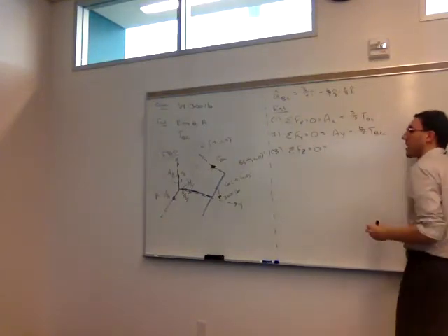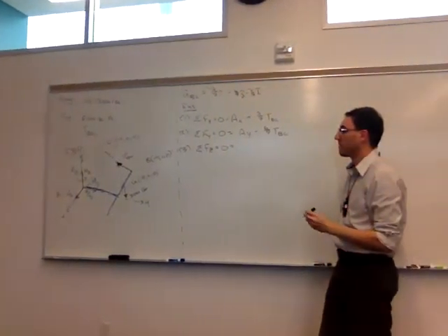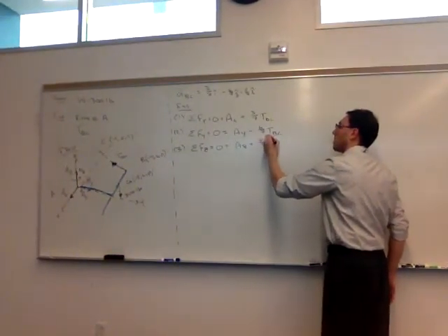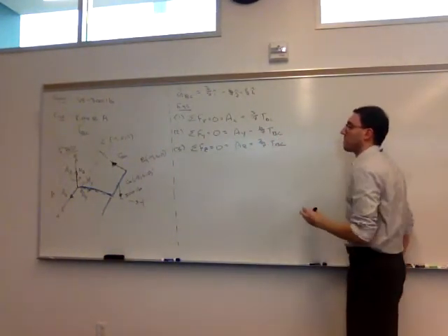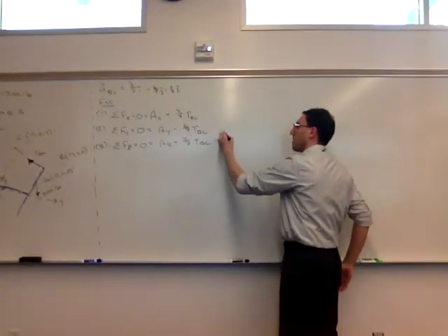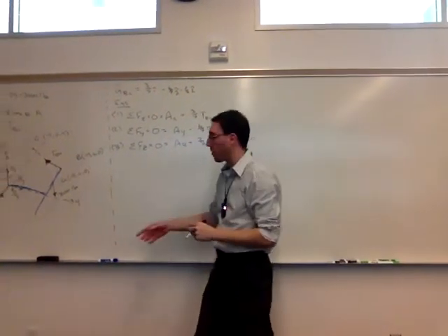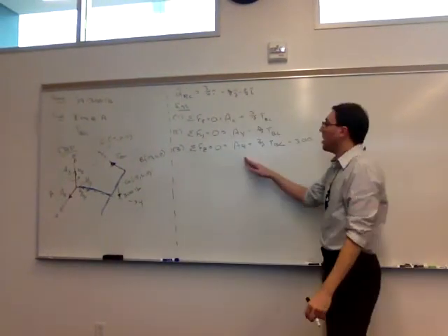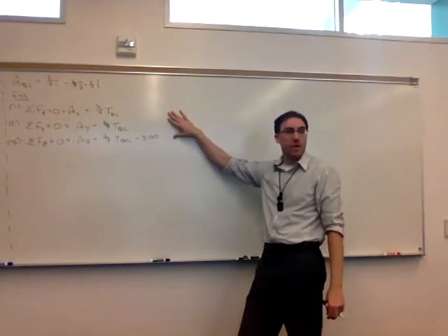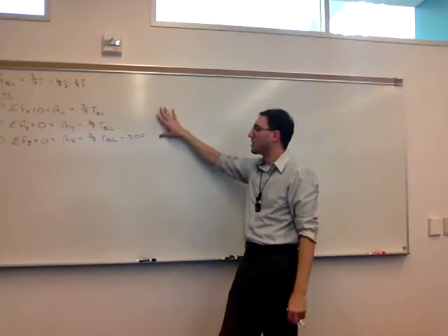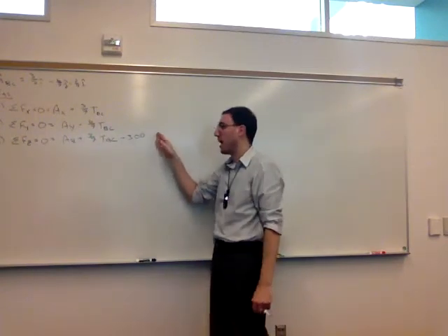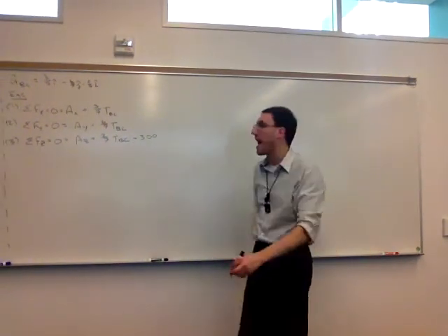So finally in the z direction, okay, one more piece. Right, so the applied force, or the weight force of 300. So from our force equations, we have 4 unknowns and only 3 equations. So right now there's not much we can, numerically we can't solve anything yet. It's too many unknowns for the number of equations we have.